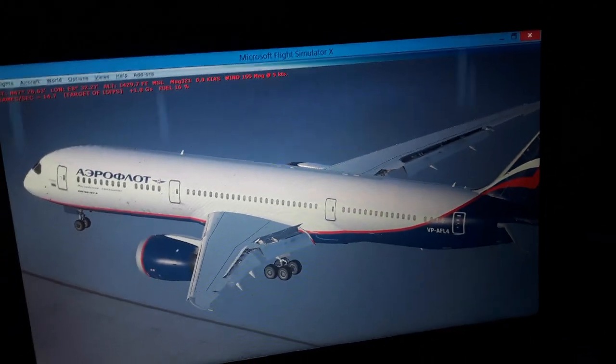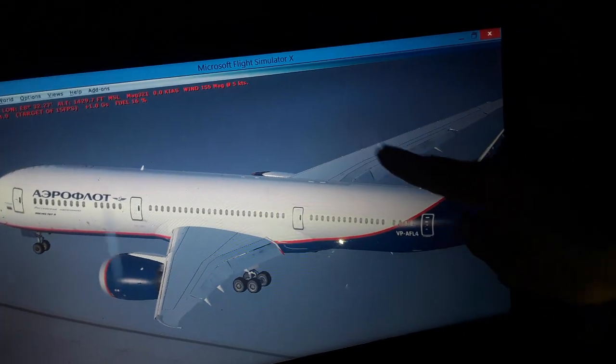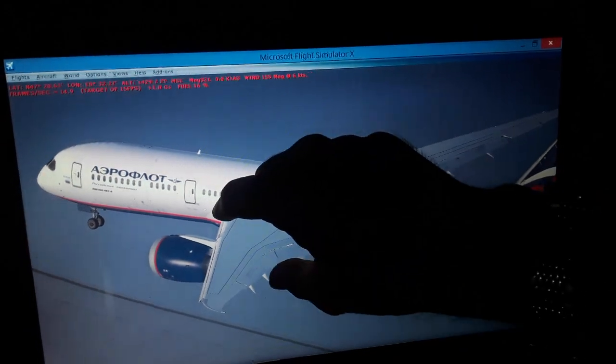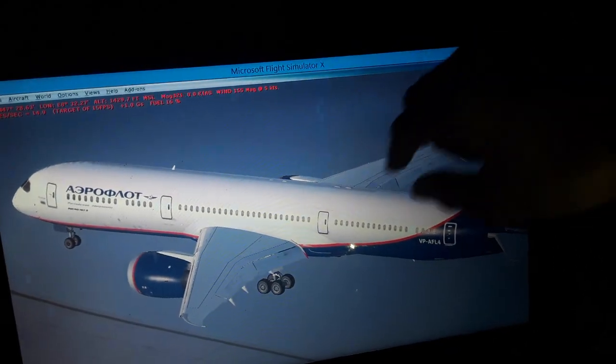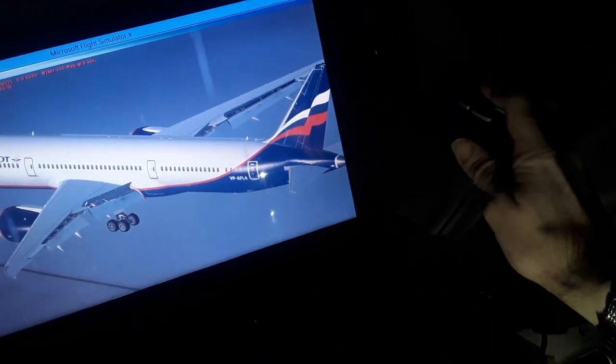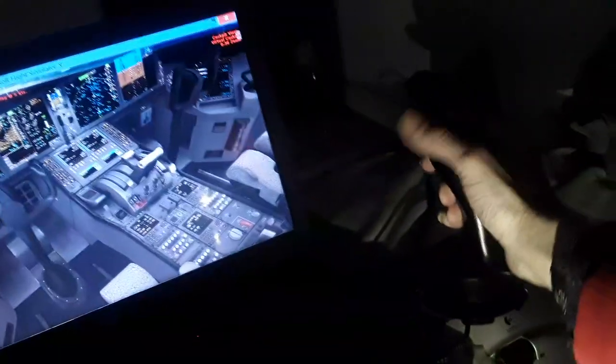So we have also the top surface of the wings, you can see it's more curved. So using the Bernoulli theory of fluids, the airflow will be moving much faster above the wings, so we have lower pressure, which sucks the aircraft weight and wings up into the air. So this is basic aerodynamics and flight dynamics you need to know when applying the thrust and controlling the aircraft using the flight controls here.